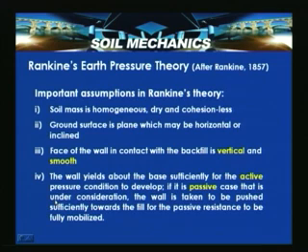Another important state which he defined is the possibility that the wall moves away from the fill, and that particular state is defined as an active state. If the wall moves towards the fill, then it is defined as a passive state. The wall yields about the base sufficiently for the active pressure conditions to develop, and in the passive case, the wall is taken to be pushed sufficiently towards the fill for the passive resistance to be mobilized.